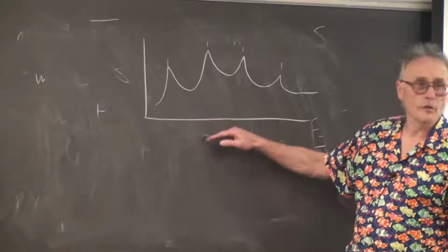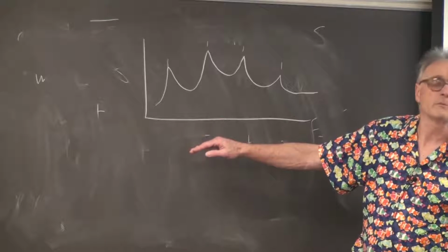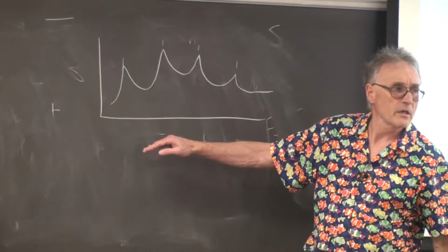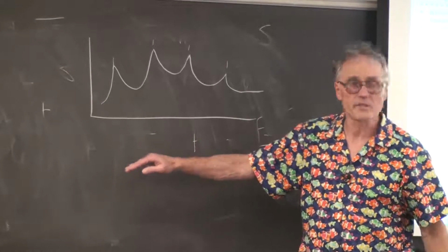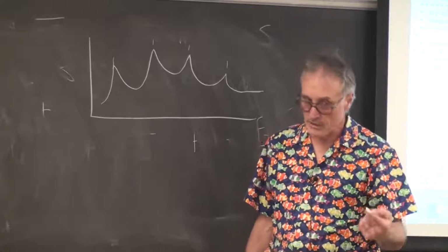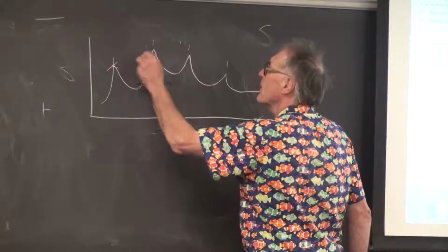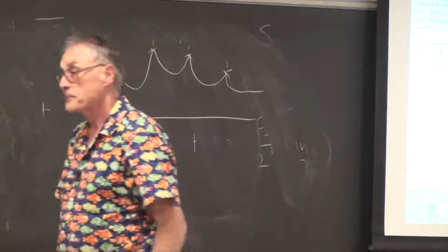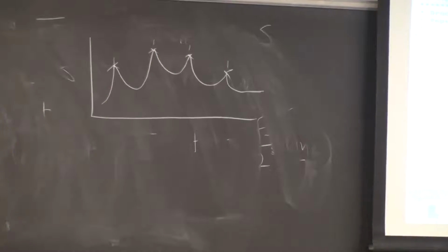So it does what's called an autoregressive fit. You know that from signal processing? It does an autoregressive fit of the signal to find an all-pole approximation of the spectrum corresponding to the resonant frequencies of the throat and their amplitudes. And that's what it sends. This is suboptimal, but it's a lot easier.